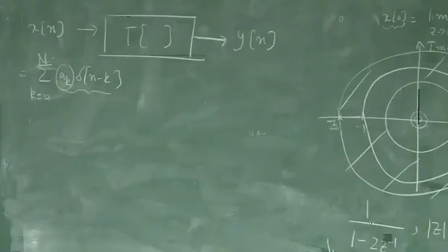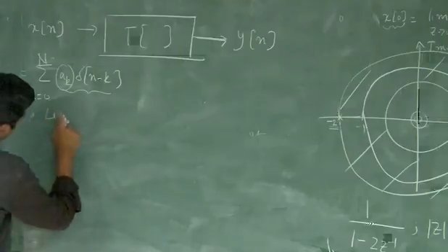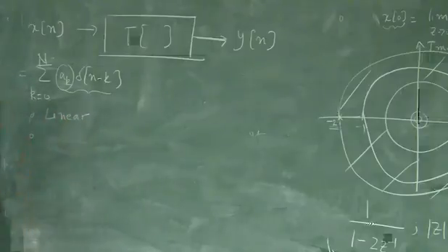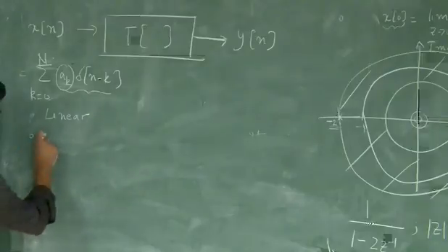We want our system to be linear so that when I have a combination of signals that are going to hit the system, the output should still retain that linear combination, correct? So we want our system to be linear, right? Next, I want my system to be time invariant as well, right? So essentially if I speak now, pause for a few seconds and say the same thing again, you shouldn't be hearing different things on the microphone, right? So our system must be time invariant